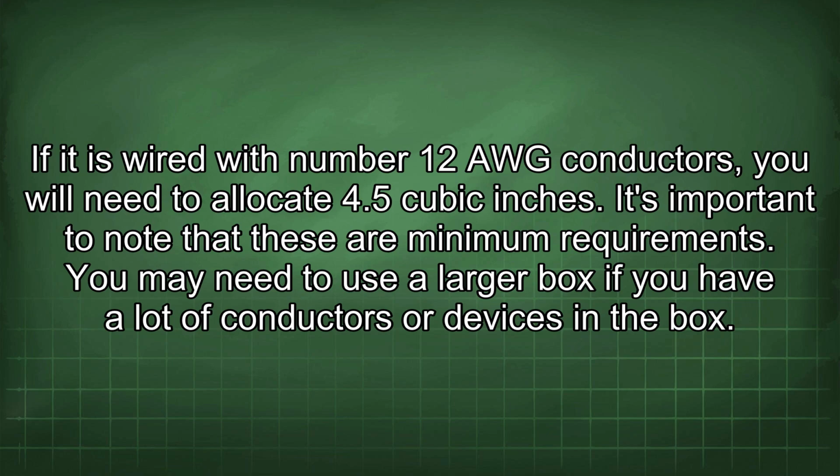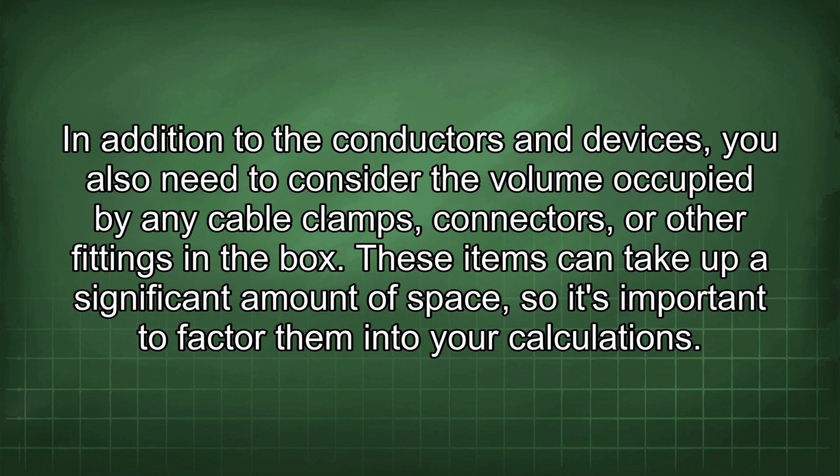It's important to note that these are minimum requirements. You may need to use a larger box if you have a lot of conductors or devices in a box. In addition to the conductors and devices, you also need to consider the volume occupied by any cable clamps, connectors, or other fittings in the box. These items can take up a significant amount of space, so it's important to factor them into your calculations.